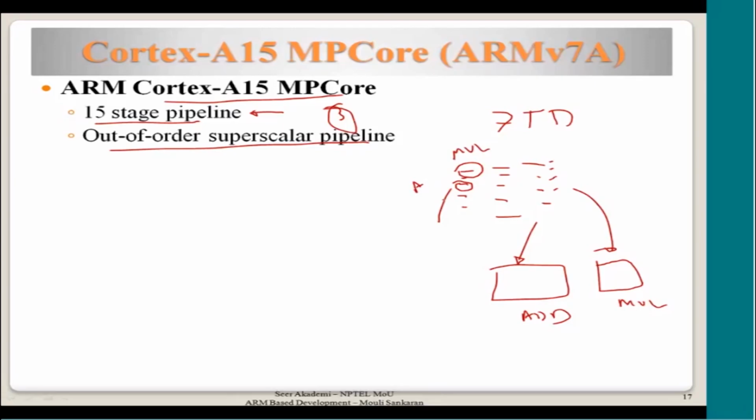But correctness is assured because the later instruction is not dependent on the previous instruction's execution. What we gain is that the processor keeps all the execution units busy executing instructions. It dynamically schedules the instructions, improving performance.